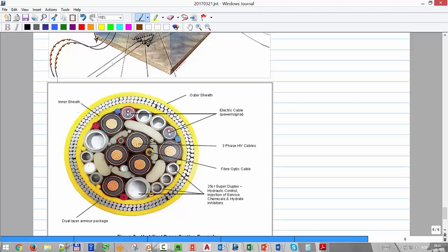So don't mind too much about the structure, okay, but it has a sheet that is protective. It has also insulation, some plastic sheet, and then inside has what really matters. Okay, so first you have the power cables. You have some valves that need power, that are electrically activated. Then you have communication. You have sensors of pressure, temperature, flow meter, sand detector, that are there, so you have to get the signal from them.